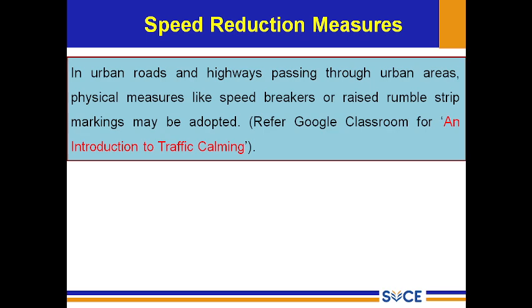It is widely accepted that differences and variation in speed, direction and mass or weight of vehicles are some of the key determinants of the severity of road accidents, especially the speed. Many studies indicated that over the past 20 years Europe became much safer with a criterion of 30 km per hour in work zone areas, with a reduction in the number and severity of accidents.